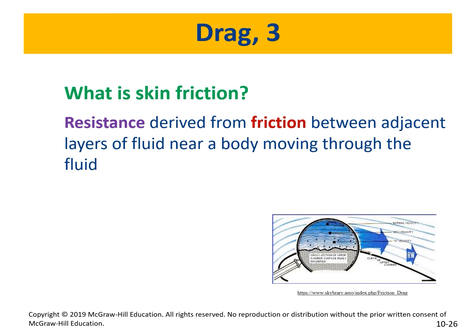So here's the thing. Look at this picture. If I have this as, let's say, the airplane wing, and you have the laminar flow of the air around it, if it's not 100% smooth, if they're not smooth, see these small turbulences that are taking place close by the surface? That is going to create a drag, which is a resistance force. So the disturbances or the turbulences close to the surface create a drag. And that's substantial, especially when you increase the speed.